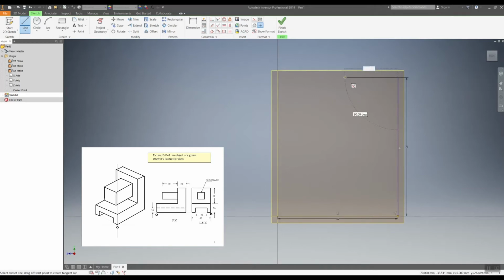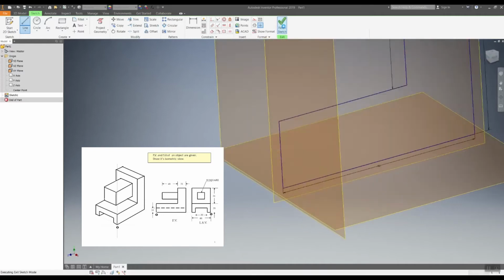This is 20 thick, and then this is going to go down. If we look, it is 20 until that mark. So I'm going to go down 50. I can simply go over, dash lines means I'm all lined up. Click down here, yellow dots everywhere. That looks good, means I have a closed object. So I'm going to finish my sketch.